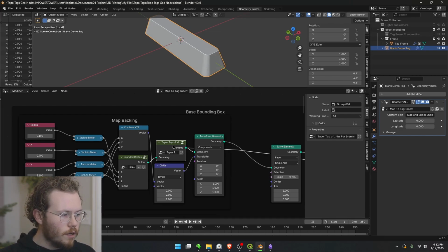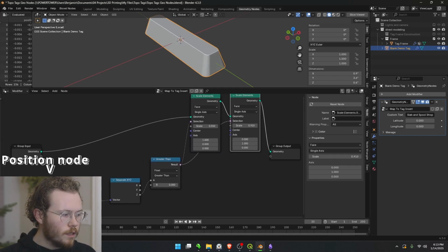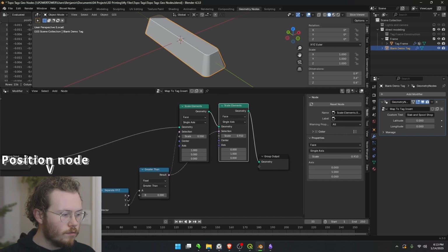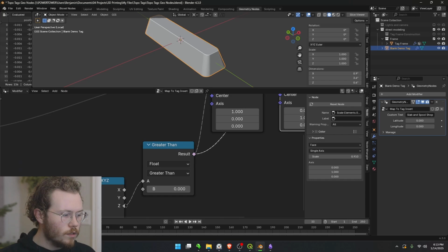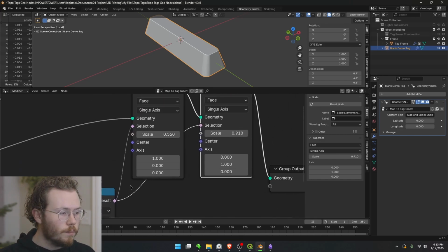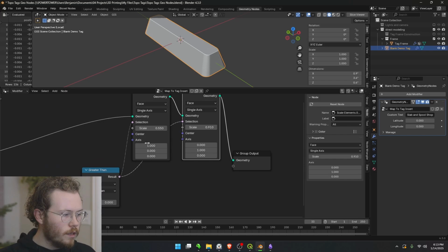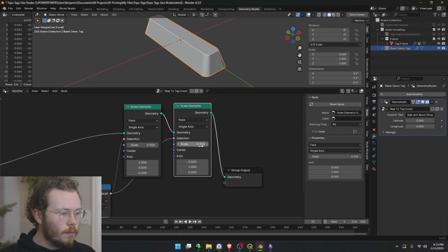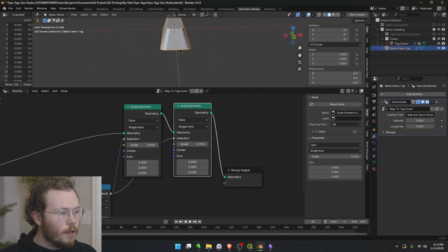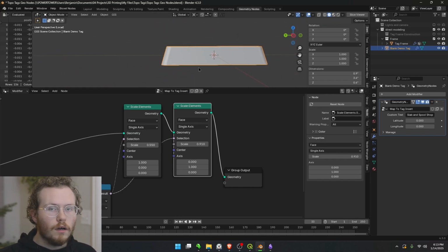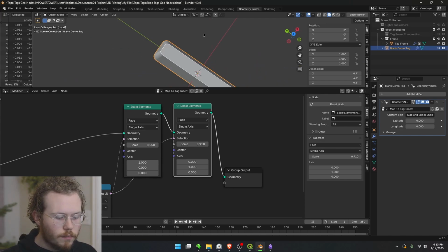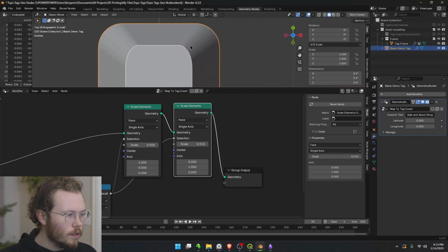see, tapers it. This one, all it's doing is it's selecting vertices by the position. Right here, it's anything with a z position greater than 0, and it's scaling it along the x, or along the y, and along the x by 2 different scale factors. That makes it so that the width and the length are more even, and we can look at that.